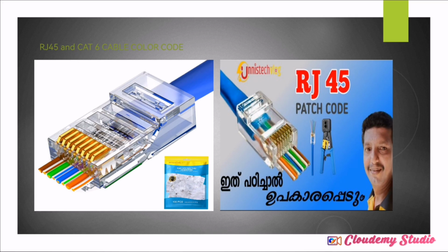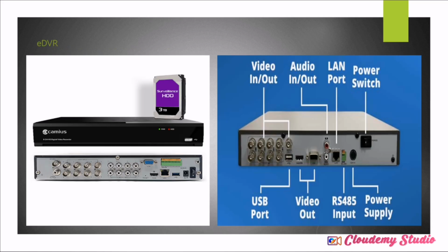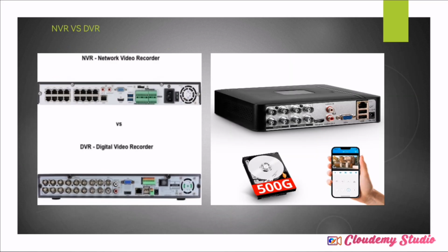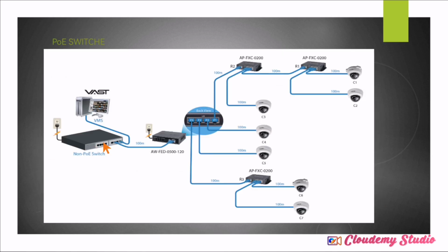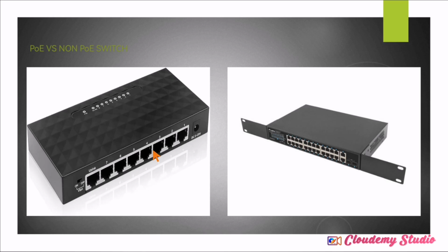Some clips will exceed and pass through up to this side outside, so that you can be sure the cable has reached the end here. Then from there you cut it here, using the crimping tool. It has the function where you can cut it and crimp. Make sure these terminals go inside in order to fit this LAN port.